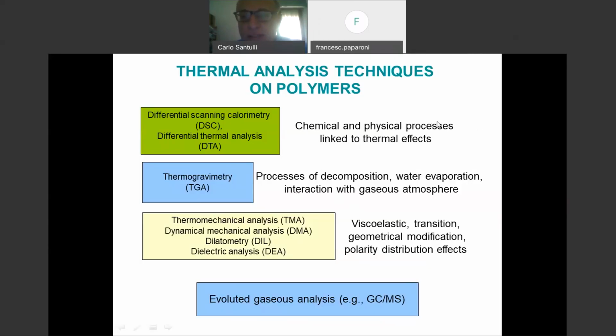Okay, this afternoon we are talking again about polymers and trying especially to see which techniques allow making measurements on polymers. In particular, concentrating on thermal analysis, which is very critical on polymers since they have a softening temperature and even a degradation temperature which is considerably low. Most of them tend to soften at around 200 degrees or less, and they degrade just over 300 degrees or so.